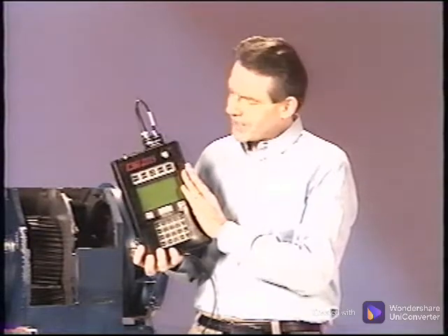A single-channel vibration analyzer such as this one can be used to determine the gear condition and pinpoint the problems, as well as determine the severity of the problems. We will use spectral and waveform data to show how to distinguish these faults and outline the best setups and measurement point locations for acquiring the best data for accurate diagnosis.